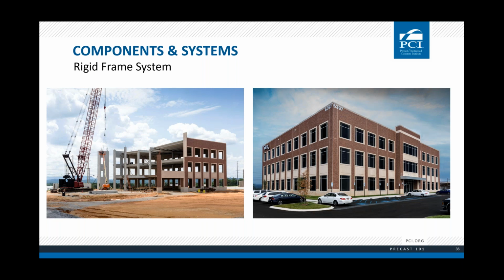And actually, the exterior panels are serving triple duty here. It is your structure, it is your enclosure, and it's your architectural appearance. And when you use a fully insulated panel, it could be your interior finish also.